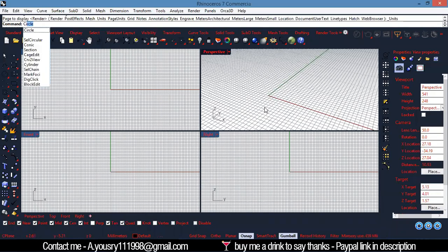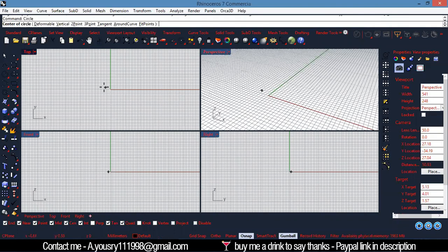Okay, so I go to circle and I need that to be at my origin point. There are two ways to make that. The first way is to type 0 and hit enter, so it goes to my origin point, or I can type 0, 0, 0, which means 0 in all axes, X and Y and Z. To make that easier for us, I'll just type 0 and hit enter, and that is going to be 60.